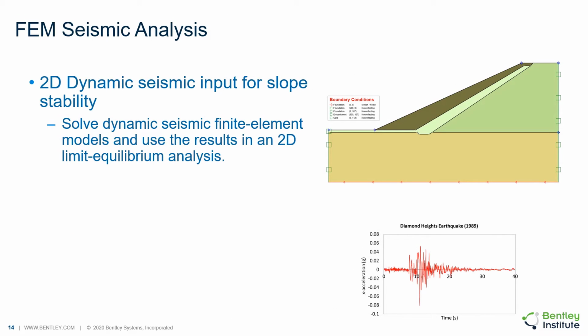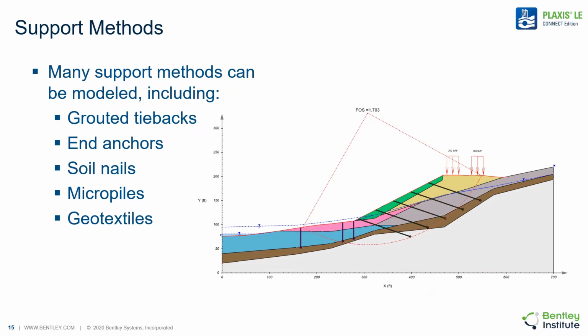There is also a finite element seismic analysis implemented with the software, and in this case you can flip to a fully finite element module where you can put on boundary conditions, apply seismic loads, solve a 2D finite element analysis, and incorporate those results into your limit equilibrium analysis.